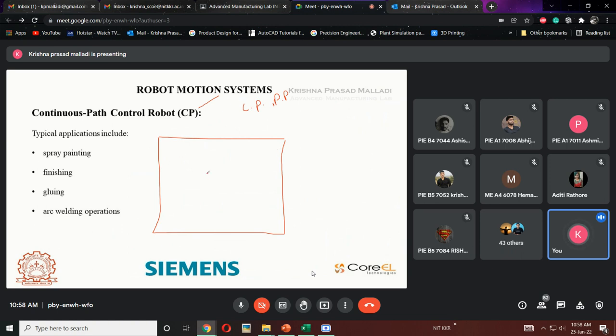You want to remove the complete excess material only, not considering this path. This is like this. This circle you have to leave and you have to remove the excess material. So you have to remove some 2 centimeters. So the path will be like this. On the top surface you have to remove 2 centimeters of excess material.